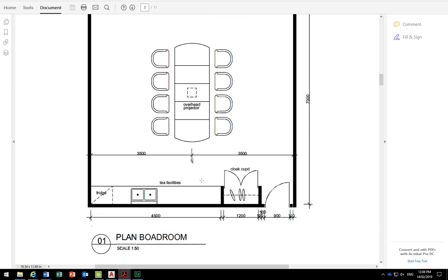So the most common standard for benches is 600. 600 deep. That's the one you should use if you can. The other one's 550, but only do that if you really have to. And a lot of appliances and other things won't work with that. So 600 is better. They even have fridges now that'll fit in 600 built in.